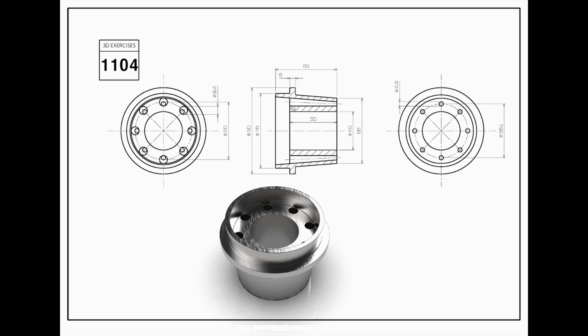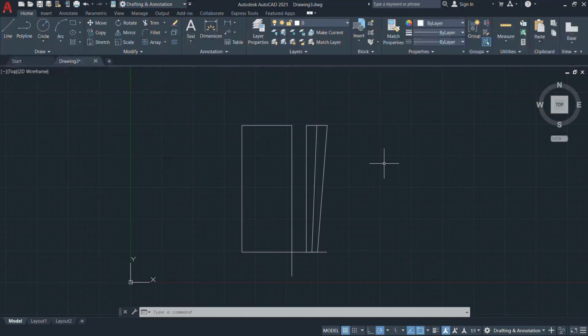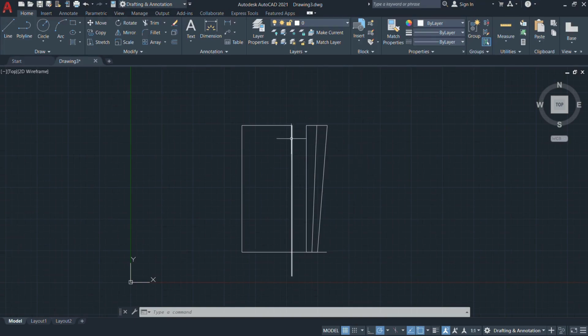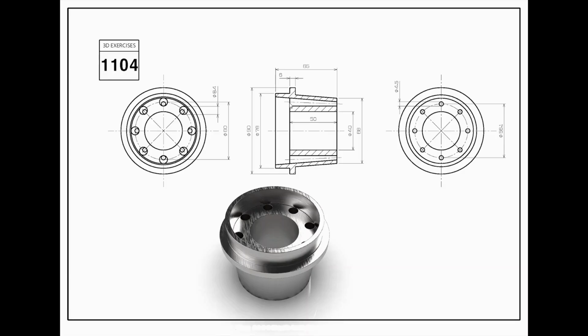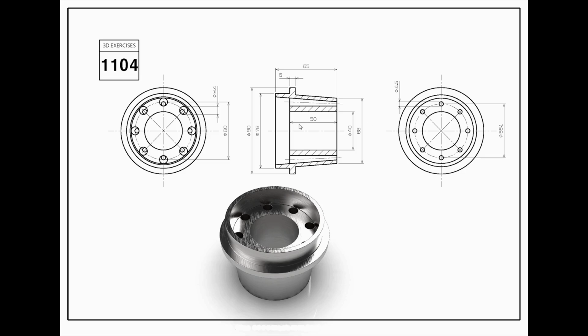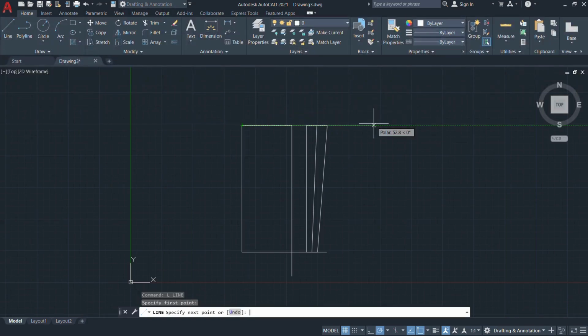Okay. Now look at the area. There we have some outer zones we need to draw from this exact area. Look at these portions. In the outer region, the overall diameter is 90 mm. So select a line profile and start from its endpoint. The overall diameter is 90 mm. Half of the value is 45 mm. So mention only 45 mm.